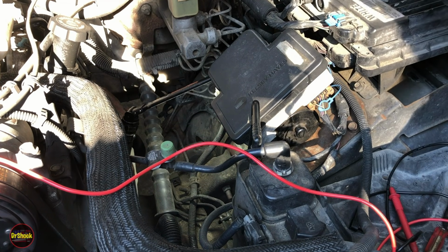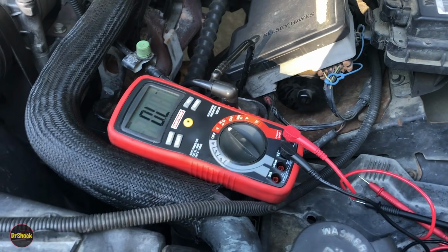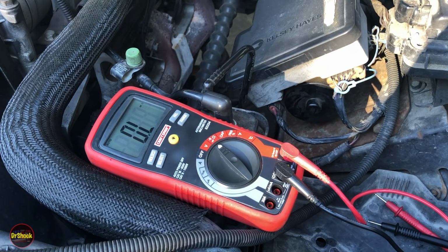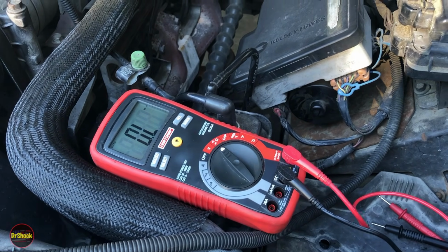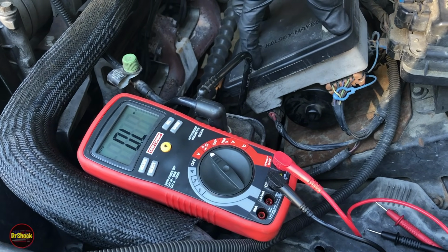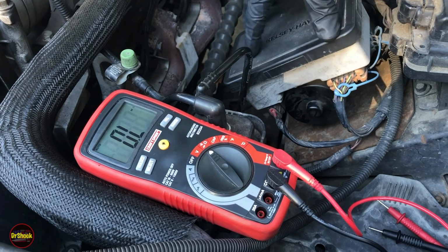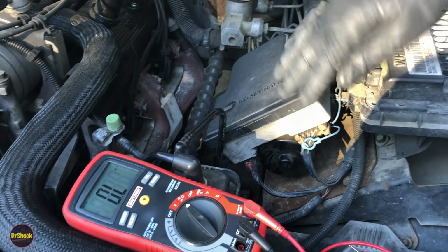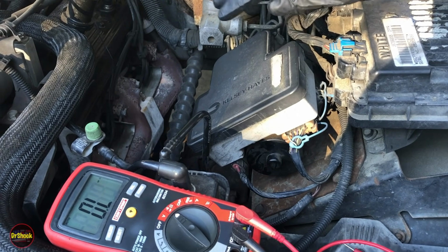And that'll let us know where we landed. But either way, we're pulling this. So let's go. All right, guys, we drove the truck and we're still getting the code. So flat out, the EBCM is bad and we're going to have to replace it because our grounds are good, and everything with a code with this top component of the EHBU is going to end up being a replacement of the EBCM. These are not serviceable. When we pull this out, I'll show you more on why.